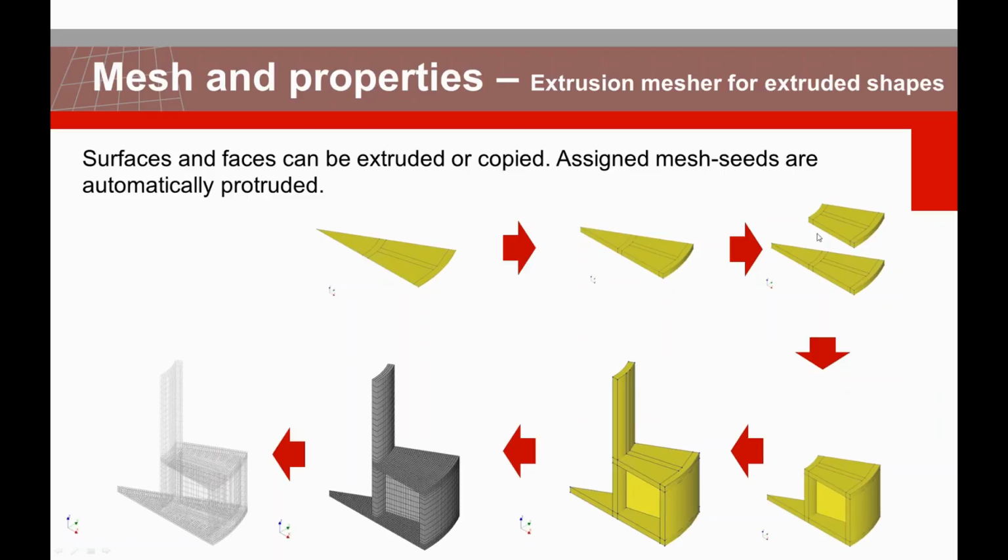Therefore, by inheriting this feature, when we mesh it, the program automatically recognizes the solid bodies which are generated based on the extrusion. It assigns the extruded mesh, and the ones that are just a solid block without extrusion go for optimization and automatic meshing. So in this particular case, you can see there is extrusion, there is a duplication of one part here, and then we have some sort of fill part.